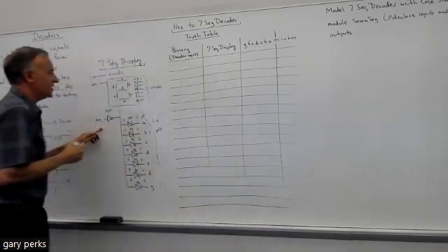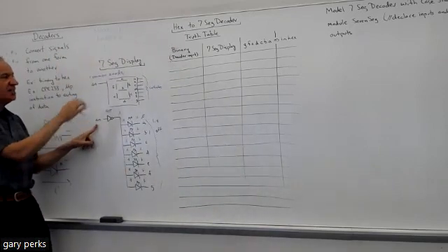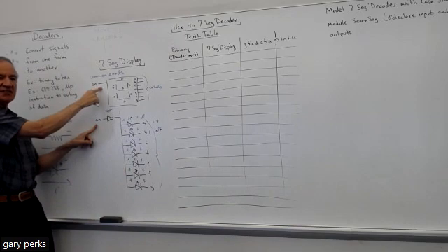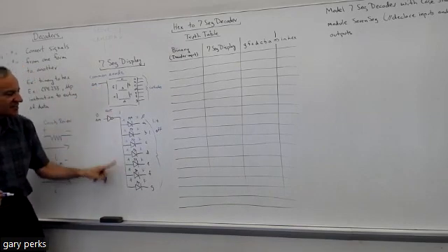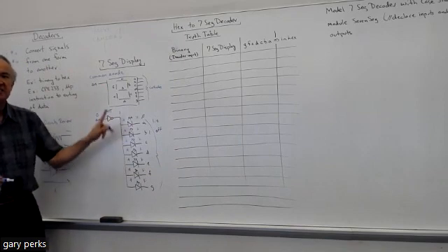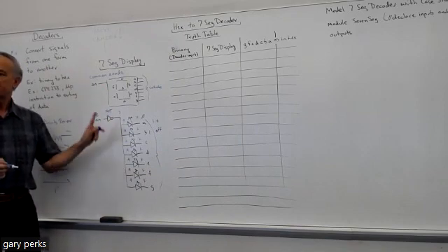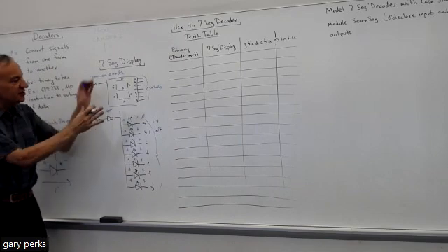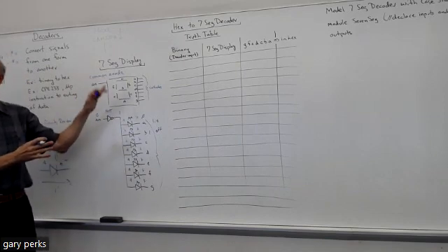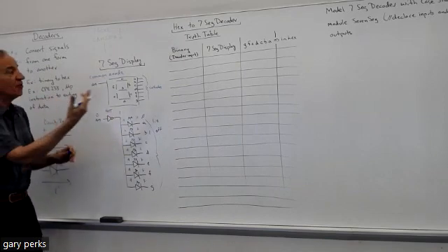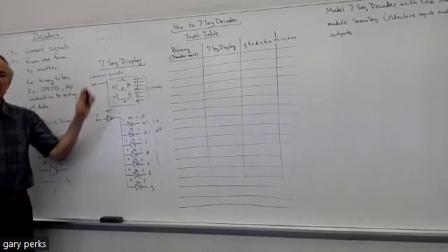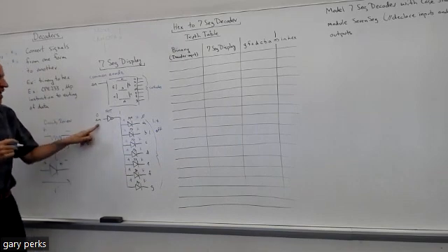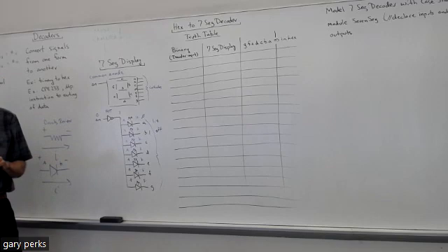So because the NOT gate's here, this input, this pin here of the 7-segment display, that's going to be a 0 in order to get a 1 on the side where the anodes of the LEDs are. Now, I just drew one 7-segment display, but all the 7-segment displays on the Basis board are connected the same. They each have their own anode and their own cathode.